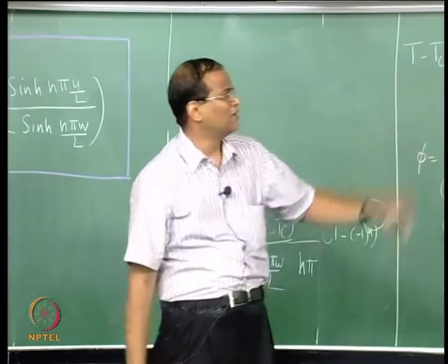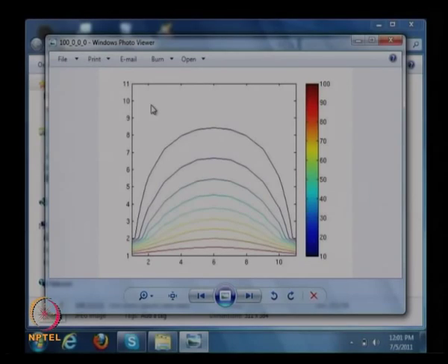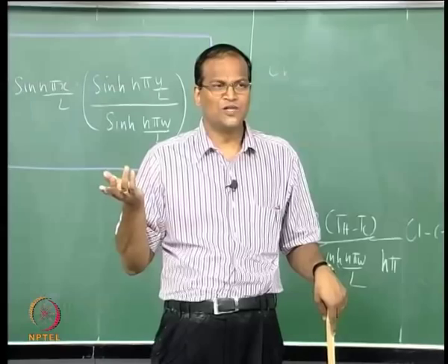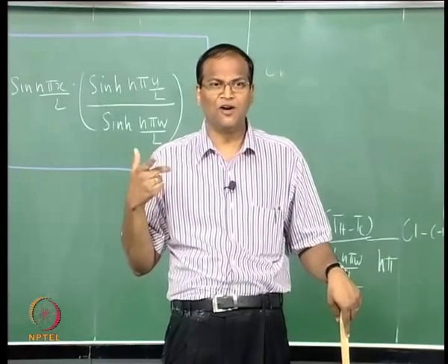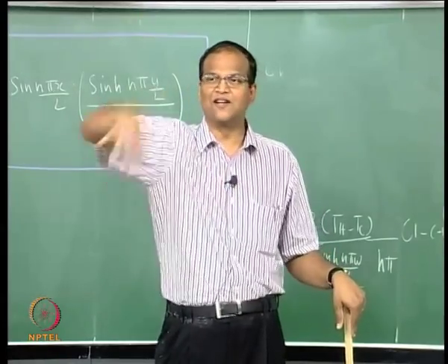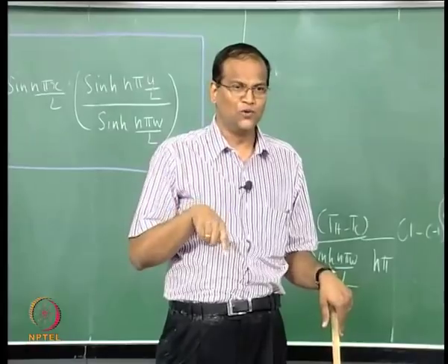Okay, so please look at this graphic. So this gives a solution to the problem, this problem for a square slab which is 10 centimeter by 10 centimeter. As you can see, though this is a problem on steady state conduction, the K is not at all used in the problem, the thermal conductivity. The thermal conductivity will enter the picture if you want to determine the heat flux at the surfaces, where it will be K dT by dx and use the Fourier's law.